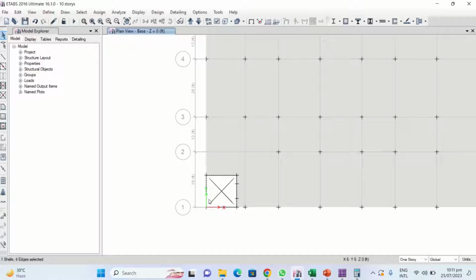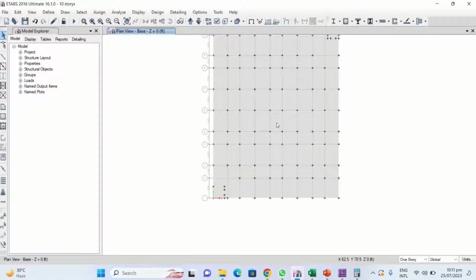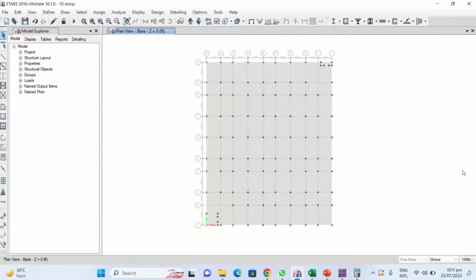So if you are in a hurry, or if you want to make it quick, whether you use the opening or you use a different section, the results will be the same. So we will be using the same thickness in the raft, but in the detailing, you will drop the level of the raft in the lift area to make it a lift pit, but the reinforcement will be the same as that you have used in the raft.